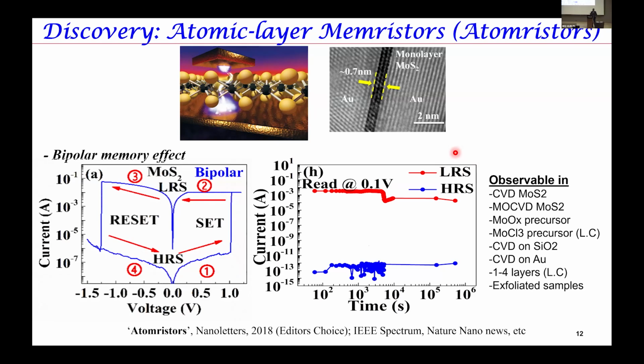Six months later, she came back with this sandwich of gold, MoS2, gold, showing the first resistive switching phenomena in this layered vertical sandwiches. And so these are typical IV curves. You have current on the y-axis, voltage. You see initially at low voltage, there's no current flowing. Then suddenly the current shoots up. This is the lightning effect. So typical breakdown field, not really breakdown, but high field, is about 1 volt per nanometer. And then you see many orders of magnitude increase in current.